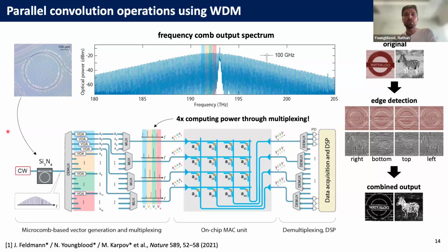Yeah, that's also a great question. So when you're designing the system, it's important to determine, is the majority of my loss due to electro-optical conversion? Or in terms of energy efficiency, is it dominated by the digital signal processing at the output? If the optical power is a very small fraction of the total power budget of your system, then it's not as big a deal if you have these combined losses, if that kind of makes sense. If these start to become a big issue, then yes, you could use, for example, microring resonators or Bragg gratings, for example, directional couplers with Bragg gratings, which would now include some sort of spectral response, which would limit your bandwidth.